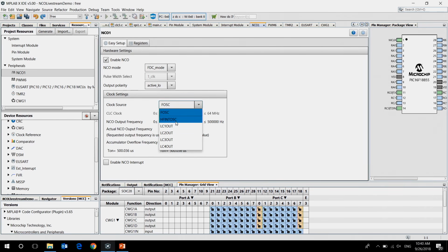Sleep mode, yes. So for those of you who don't know what sleep mode is, it's just a low power mode where you're essentially turning off the central processing unit, you're turning off a lot of the features on the device because you want to put this into the lowest power consuming mode. In fact, in most applications, especially battery applications, you're going to want to run your application 99% of the time in this low power sleep mode. So the idea is to conserve battery power if you're doing something like energy harvesting, that kind of thing. And this just gives you another capability that you can run in this lower power mode to keep it as battery friendly as possible.